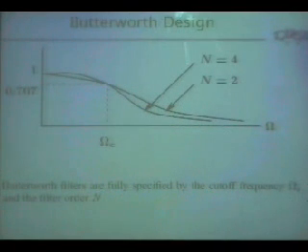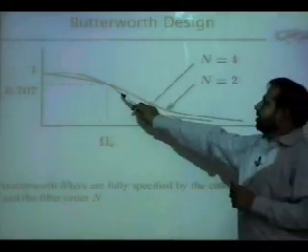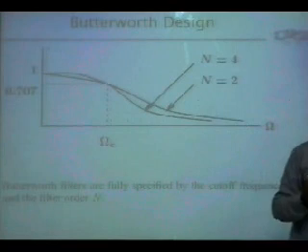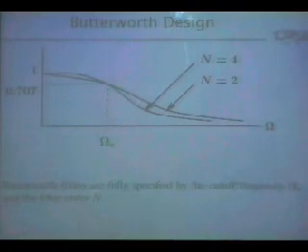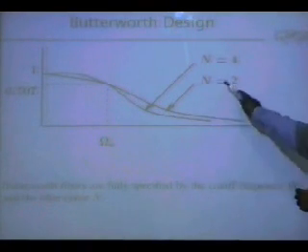Okay? So that's how, once you give your specifications, the design tool will figure out at what order filter will satisfy the design constraints. And we'll shortly see how tightening up the constraint means that the design tool will come back and ask for a more complex filter.